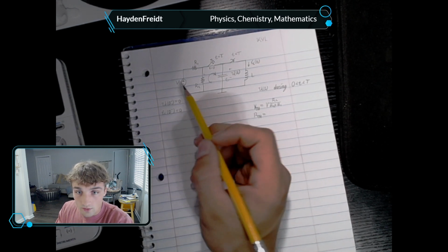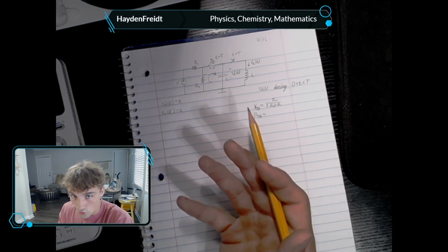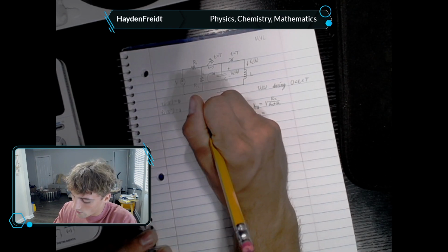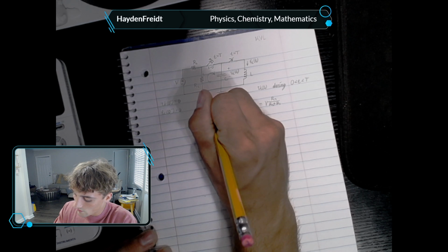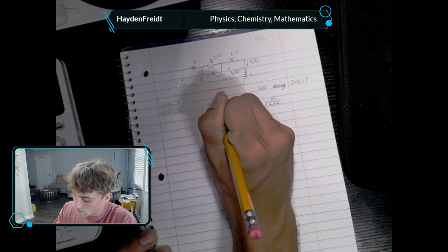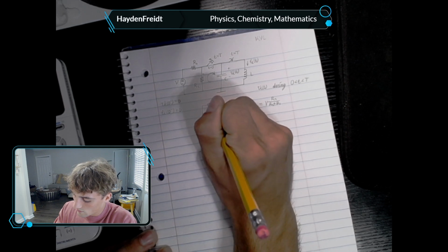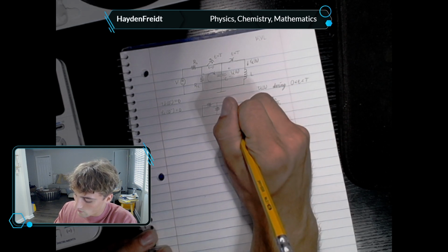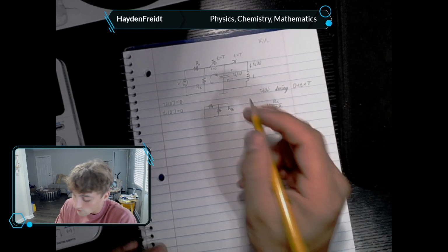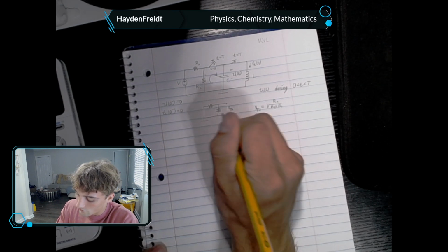This voltage source is going to become a short. If it were a current source, it would become open. Let me just draw another model. We're going to short that. We're going to have this resistor here that goes to the capacitor, and this resistor here. We want to know the resistance R Thev perceived right here. And then we'll put ground for reference.